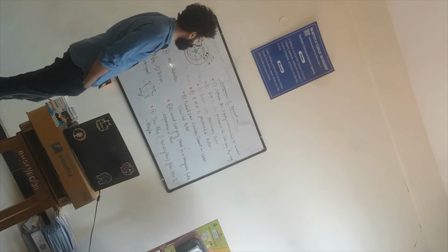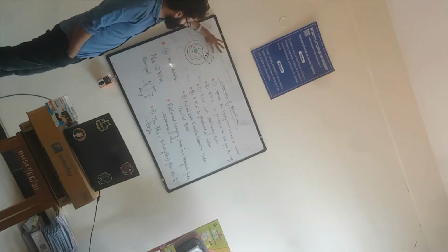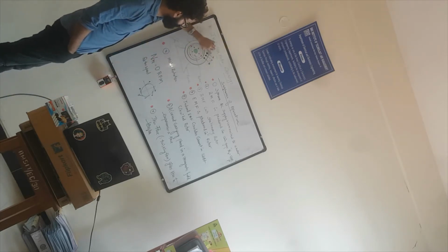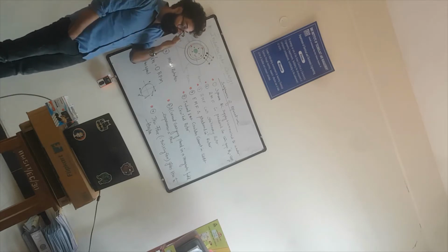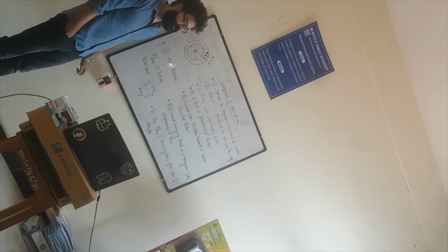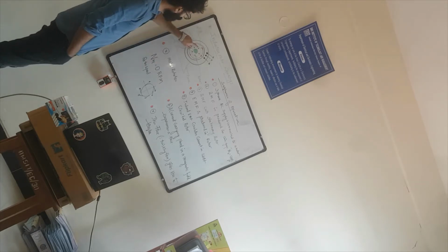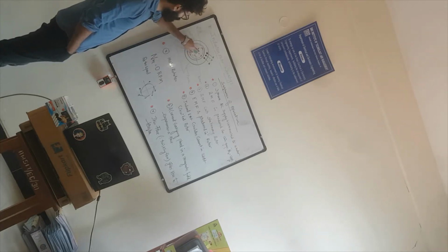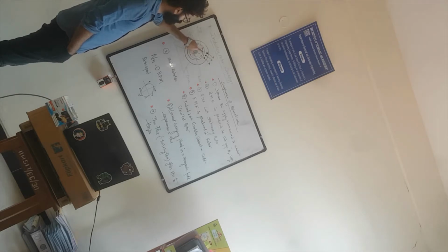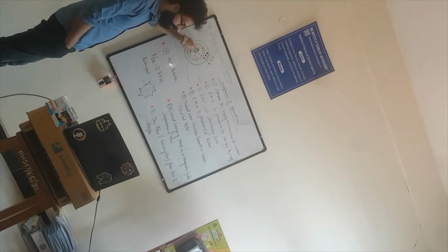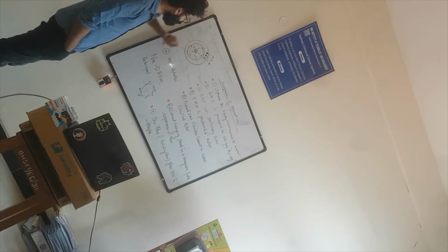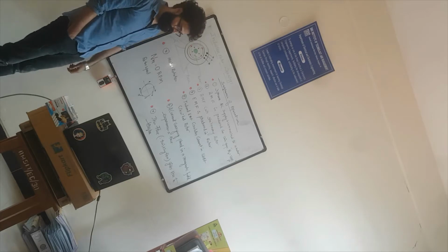Quickly let me brief up. 3-phase AC supply is connected to the stator winding, due to which a rotating magnetic field is produced. The rotating magnetic field rotates at synchronous speed, which is 120 F by P. Initially, the rotor is at rest, so the rotating magnetic field cuts the stationary rotor conductor, due to which an EMF gets induced in the rotor.